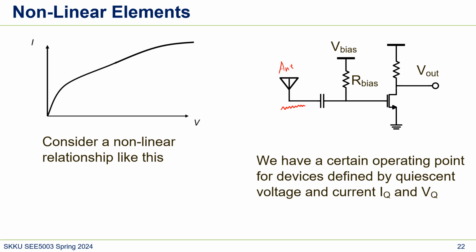But anyway, let's say just a very small signal is here. This capacitor only accepts the AC signal. So let's say the VG looks like some signal from an amplifier, antenna. And this point is important. This DC voltage is V bias, because we have this circuit. This circuit sets the kind of operating point. So that's what we call V bias.